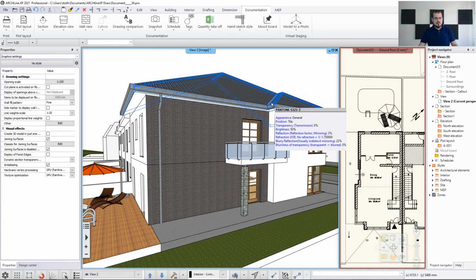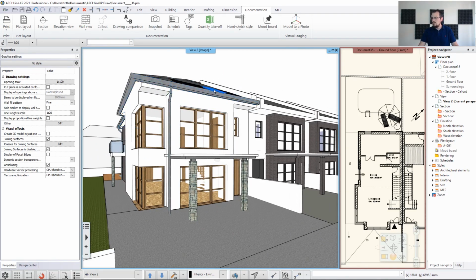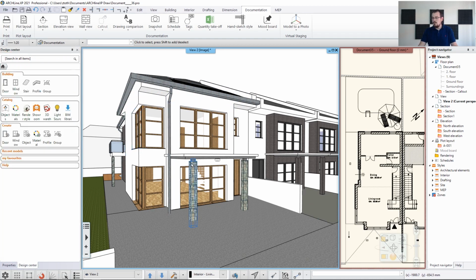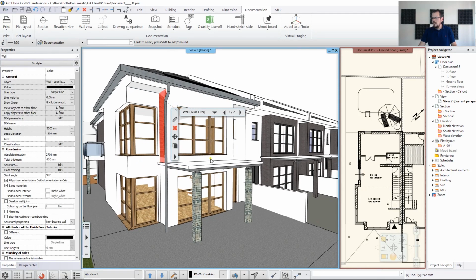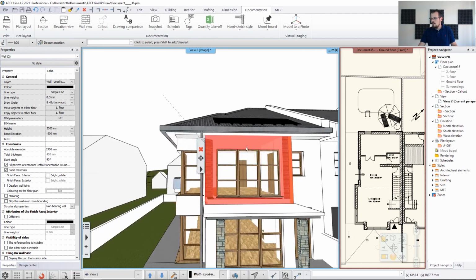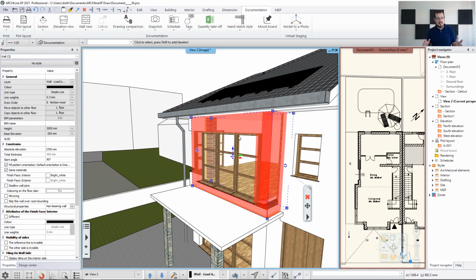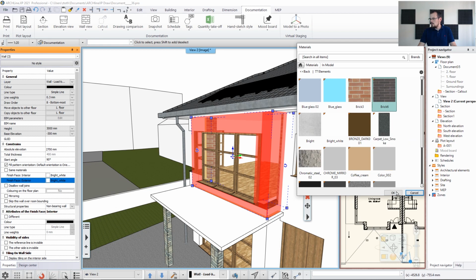Now, this might be a bit cumbersome if you have more than one wall, as is the case now. So we are just going to go out here, and I'm going to show you how to do it in one step for more than one wall. So I'm going to click on one of the walls I want to change, and I'm going to hit Control, and while navigating, hit Control again, and now I have more than one wall selected. So again, I'm just going to go same materials disabled, finish face exterior is going to be brick.